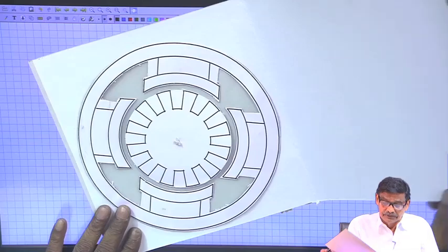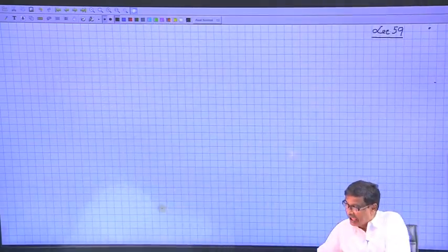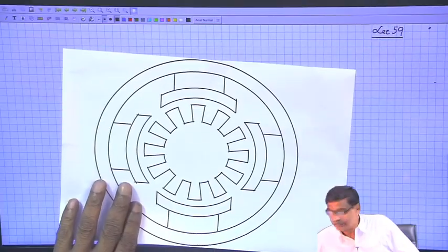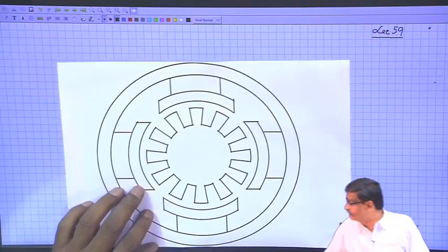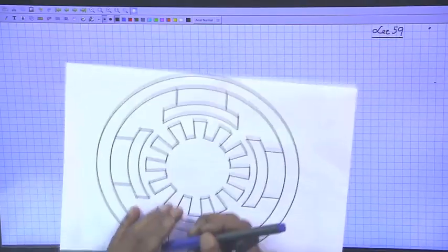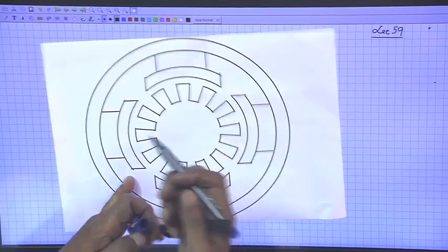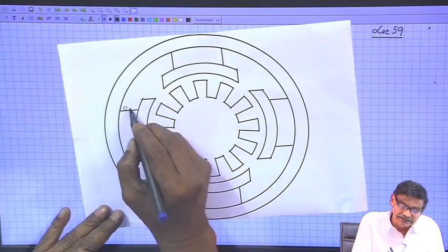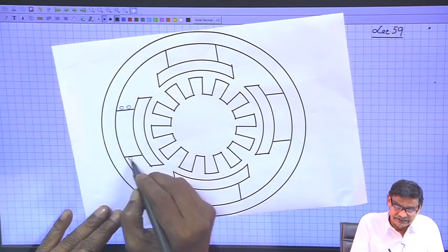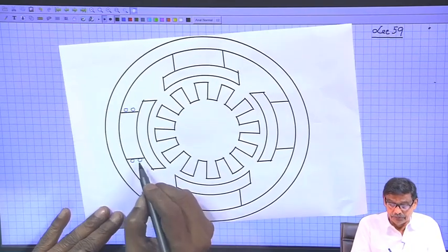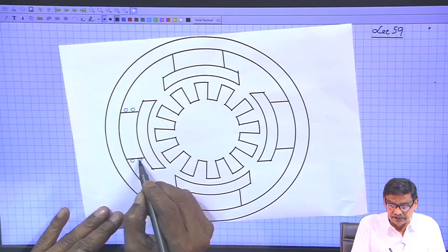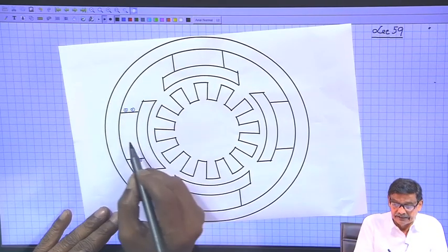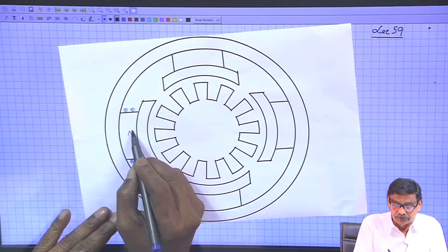Okay. So, this is the thing, and if you look at this diagram on paper, what is to be done is that these stator poles will be created by conductors placed around them. Suppose this carries cross current and this carries dot current, then this becomes a north pole.